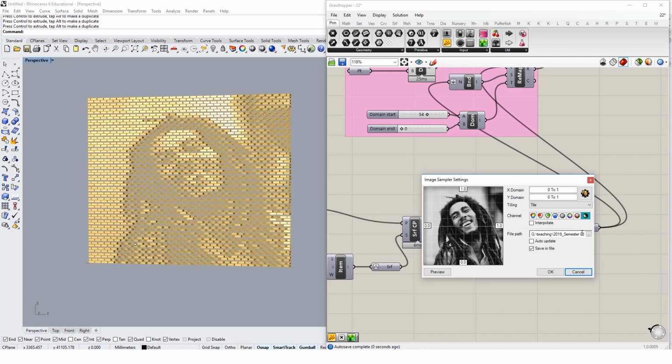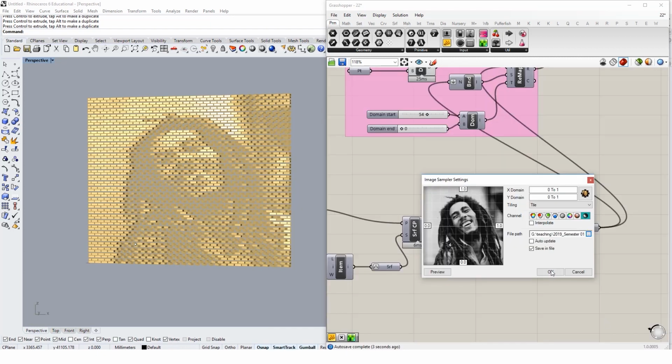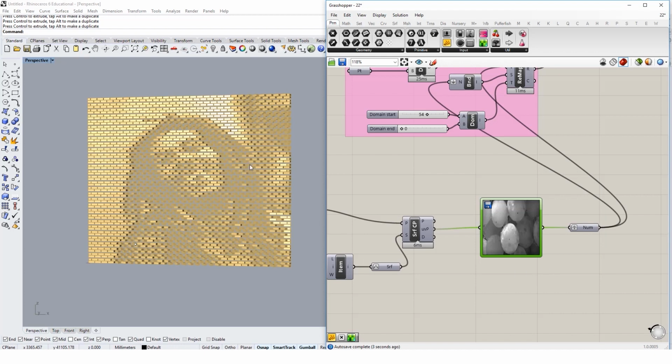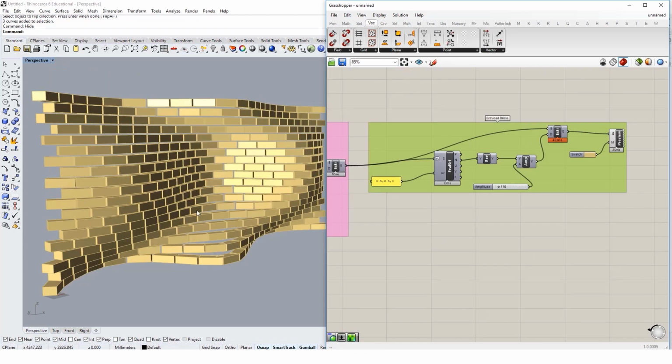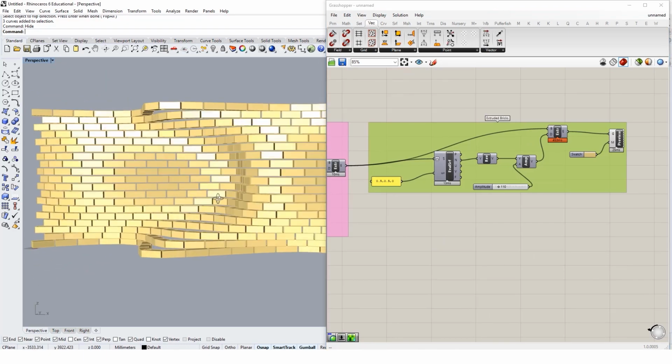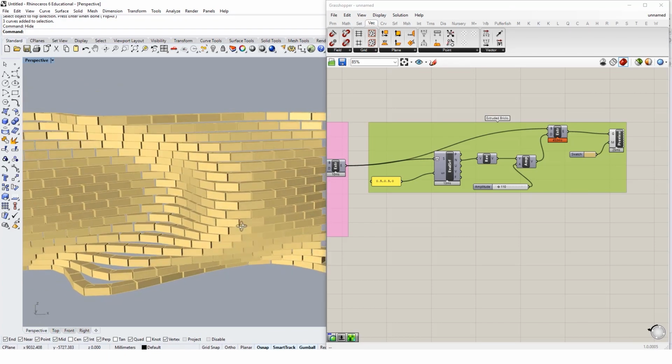After building a simple brick wall, we will attempt to manipulate our geometry to create more complex patterns and shapes whilst adhering to the parameters of the wall. We will rotate bricks using attractor algorithms, the image sampler toolkit in Grasshopper, and complex surfaces. The series will also examine the Winery Gantenbein project by Gramazio Kohler as a precedent study.